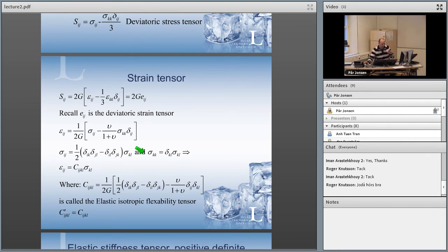So elastically, this is quite easy to do, even mathematically, because it's a straight relation. You can almost get it directly, because if you have a hyperelastic material, you can go to that point directly. You don't need to do it incrementally. But if you have plasticity, for example, then you have to do it incrementally, because then you have to divide it into elastic and plastic, and you have to know how much elastic and how much plastic is this increment giving me. But we come into that later. But right now it's quite easy to get the stresses and the strains.